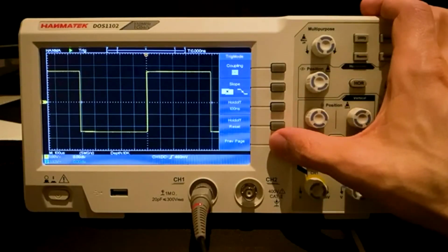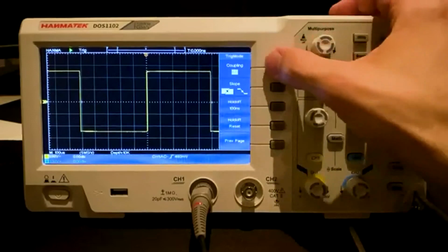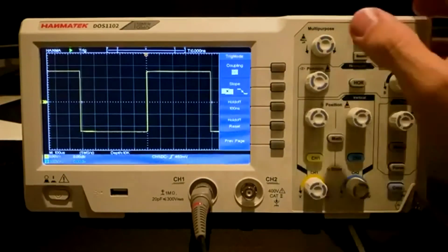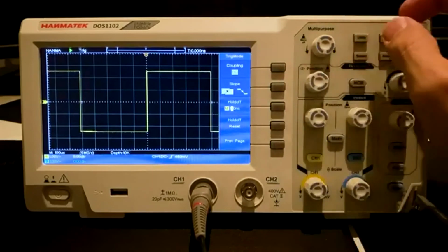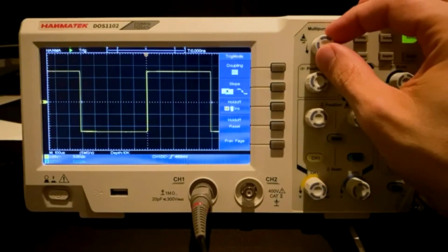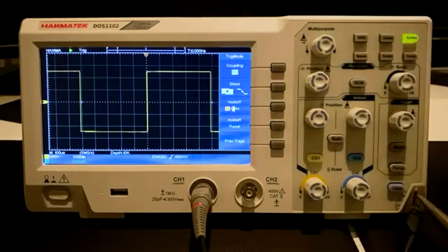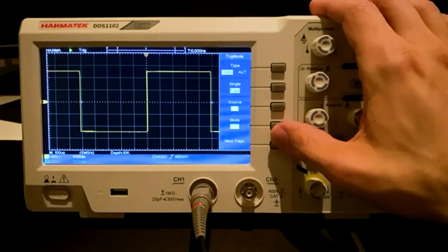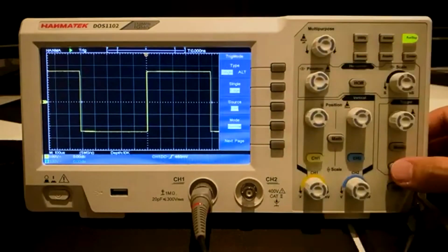Coupling is supported for DC and AC. A rising or falling edge can be selected. Hold off defines a dead phase during trigger time. Time is reset with hold off reset. Force generates a trigger signal in normal and single modes.